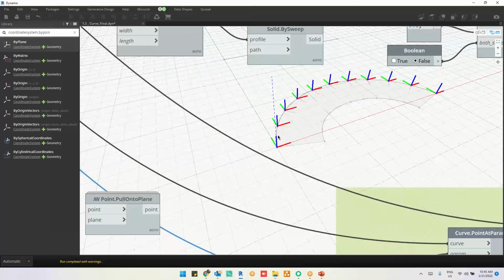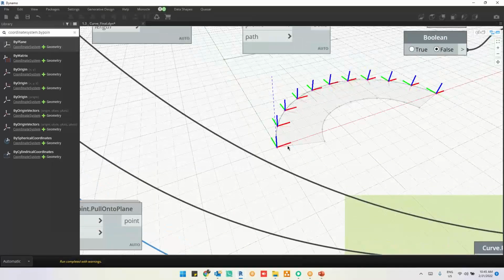It will always follow the same Revit coordinate system. So if you have 1,000 points, it will exactly maintain the same. This always would be the y, this always would be the x, this always would be the z. Clear? When you are playing with any meshes or any SketchUp models, if it has a lot of curves, this is the problem most architects are facing.